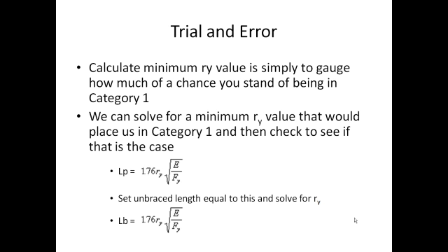And if you fall short, then that section would be in category 2, and you'd have to proceed on that trial in a longhand fashion. But anyway, that's a little technique that we can use for the trial and error method for beam design that might help you out.